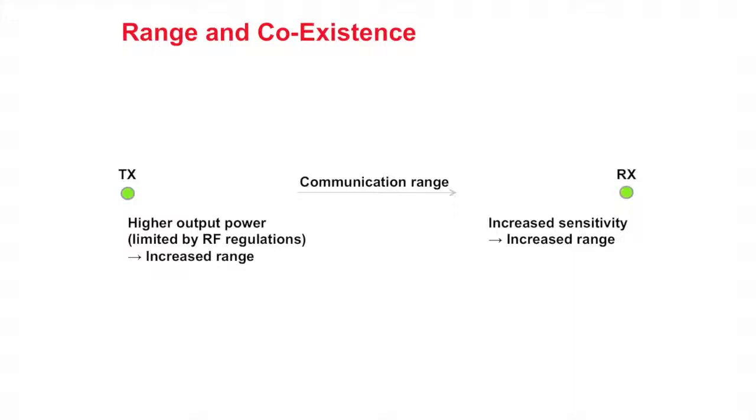The sensitivity is influenced by many factors, but the 2 most important are data rate and receiver sensitivity. Typically, higher data rate gives shorter range, so it is important to find a data rate that fits the range and throughput requirements. The receiver sensitivity is the ability to decode an incoming RF signal. Given the same data rate, a good receiver is able to decode a weaker signal and hence give better range. I will give you an example. Around 50 kilobits per second will typically give full house coverage and a good balance between throughput and range for an alarm and security system.